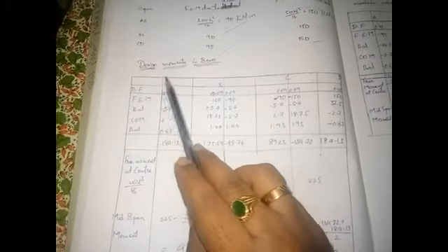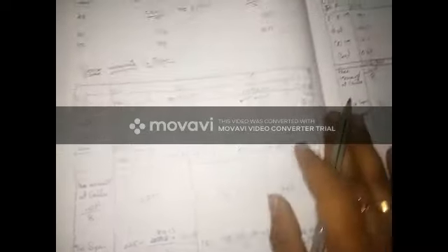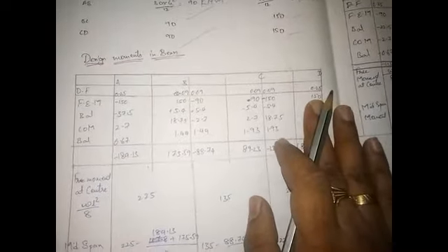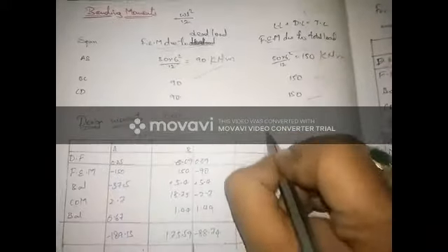Then after that, the main part here comes with respect to the design distribution moments. That is the distribution moment table or design moment table with respect to beams. As I said, we are supposed to analyze the beams with respect to two conditions: one is minimum midspan condition and the other is maximum midspan condition. So the first case we are taking as minimum midspan. As we know the midspan is BC, so we'll take BC as the minimum value.